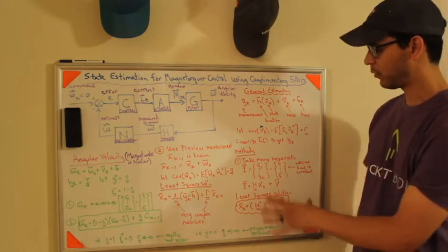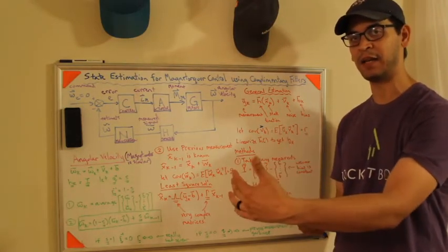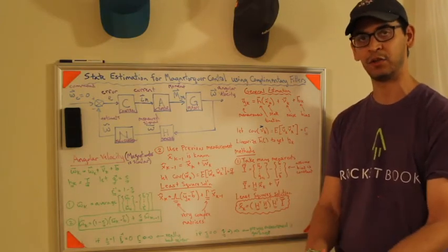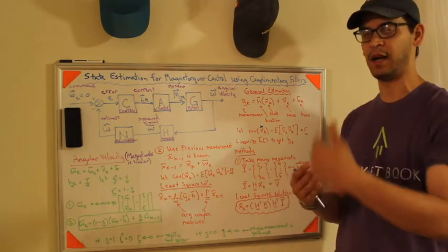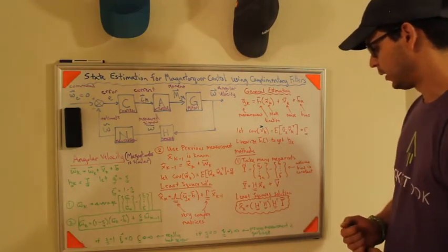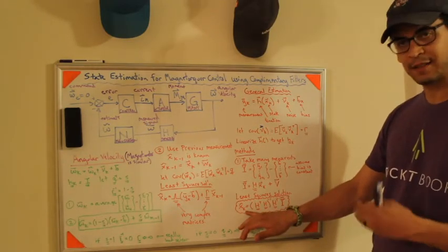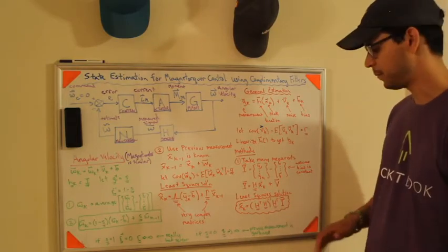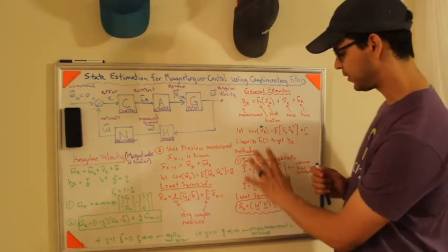Okay? And by the way, all of these equations, I'm eventually going to create MATLAB and Python code that simulates the dynamics and simulates this filter and the controller. So if it doesn't make sense right now, that's fine, we're just doing the theory. Eventually I am going to apply it and put it onto real simulation software. So again, this is the estimate of my state at the kth measurement, and it's equal to H transpose H inverse H transpose Y.